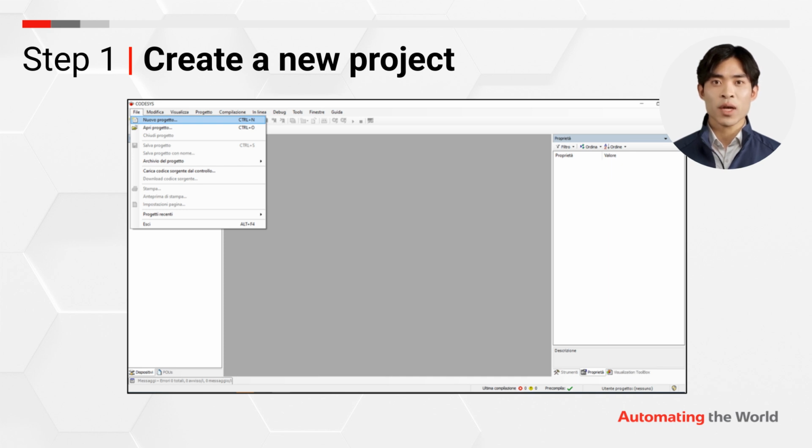First of all, after opening the Codesys development environment, let's create a new project by selecting GOC 43 as the template. After confirming, in the next step check that the device version matches the GOC 43 unit you're using, and choose which programming language the first program in the project will be generated in.